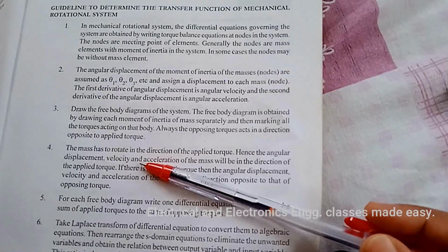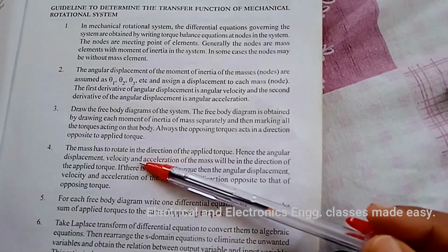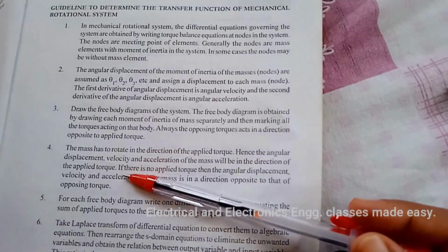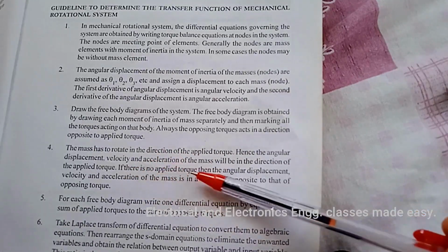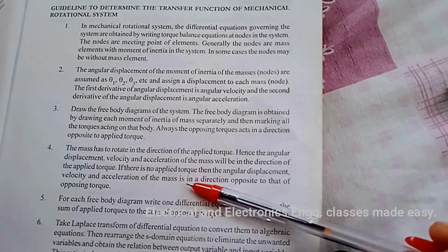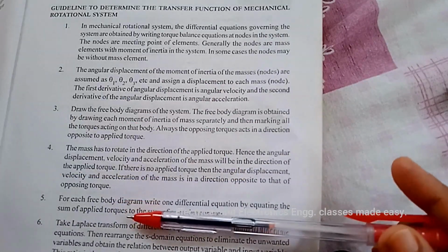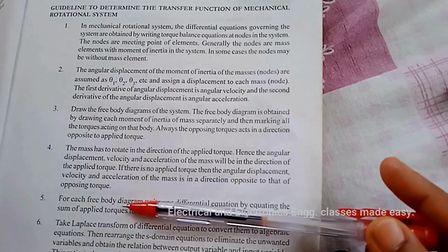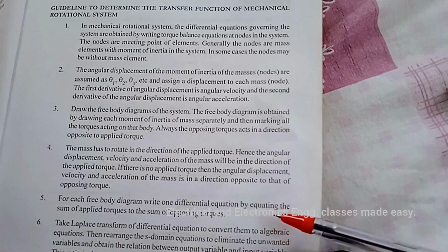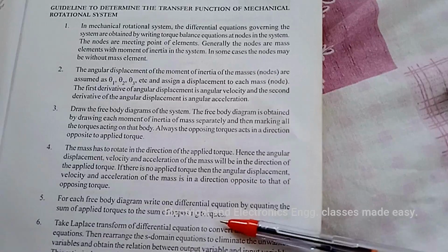Fourth one is, the mass has to rotate in the direction of applied torque. Hence, the angular displacement, velocity and acceleration of mass will be in the direction of the applied torque. If there is no applied torque, then the angular displacement, velocity and acceleration of mass is in a direction opposite to that of opposing torque. Fifth one is, for each free body diagram, write one differential equation by equating the sum of applied torques to the sum of opposing torques.